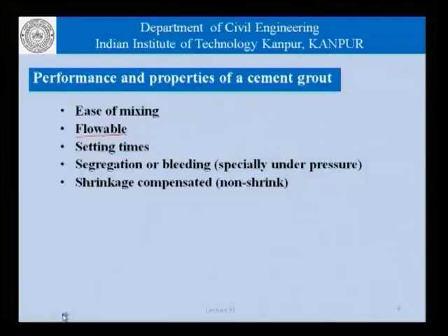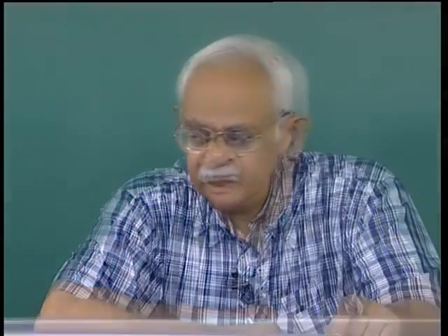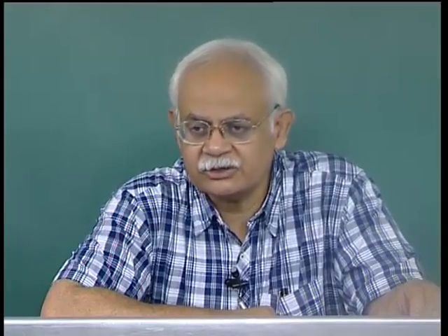of bleeding. Shrinkage compensation. Again, grouts, because they do not have coarse aggregate, proportionately speaking, the volumes of cement are much higher, and therefore, there is a tendency for the grouts to shrink, unless special measures are taken to add admixtures and so on to design shrinkage compensation grouts, that is non-shrink grouts which do not shrink.